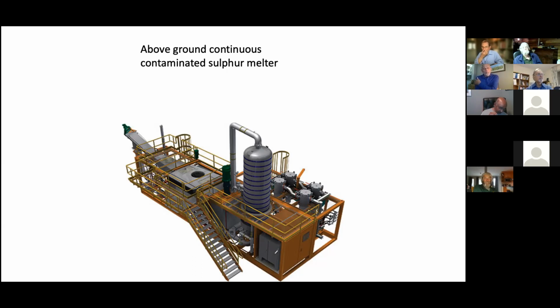And we found we could speed up the melting by a very controlled, slow rate feed into the pit. And that's what this process makes use of. So this is the melting tank right here. And this opening here is where the sulfur is fed in. And it is a conical settling tank.